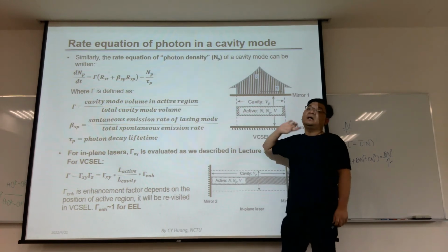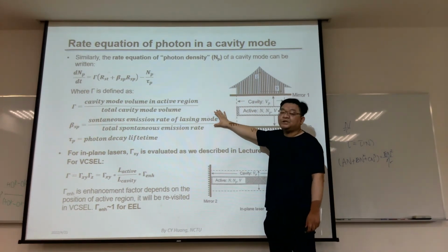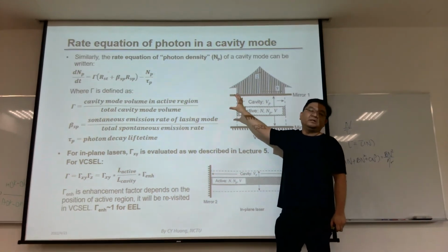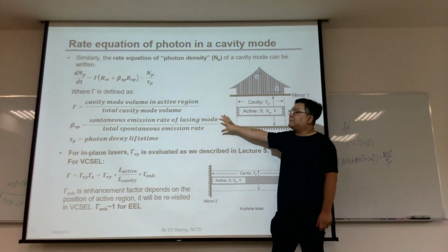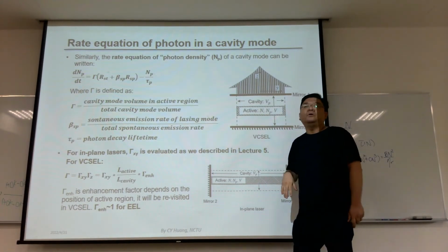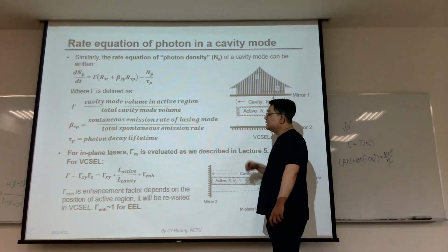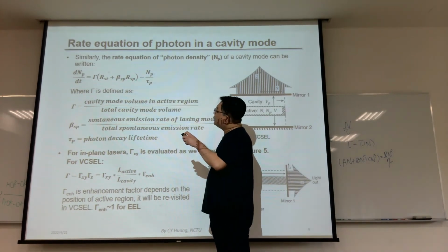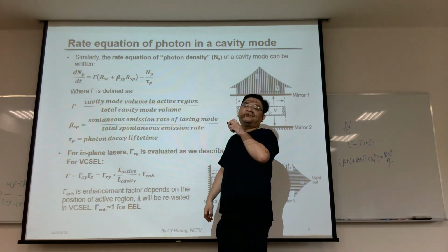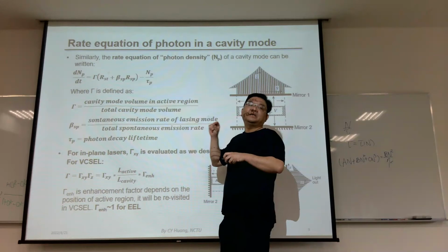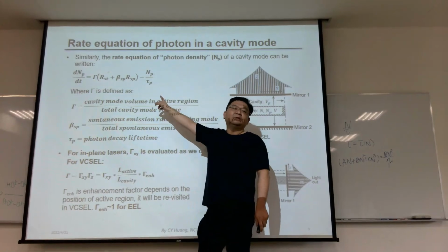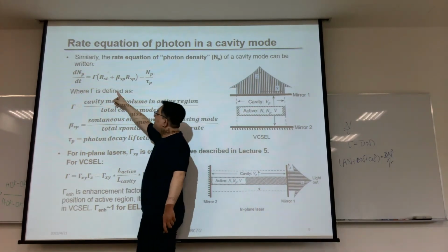That's another case. But for the edge emitting laser or VCSEL, whose cavity is much larger than the photon wavelength, this number is usually quite low, probably 10 to the minus 4 or 10 to the minus 5. That depends. Anyway, the total spontaneous emission rate needs to be times the beta SP for counting the photons in a specific mode, times the RST, because RST only applies when a mode exists, and then times the confinement factor.